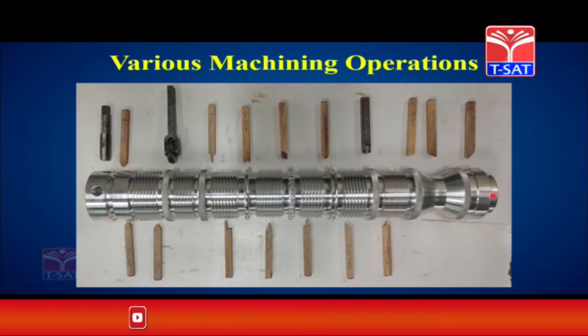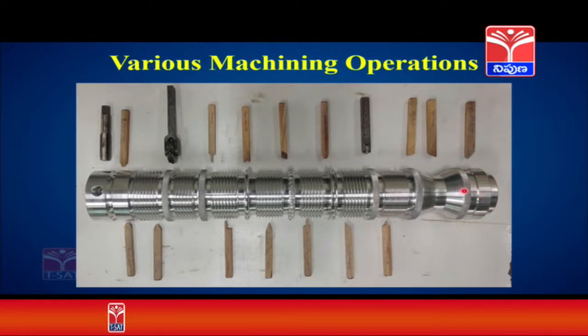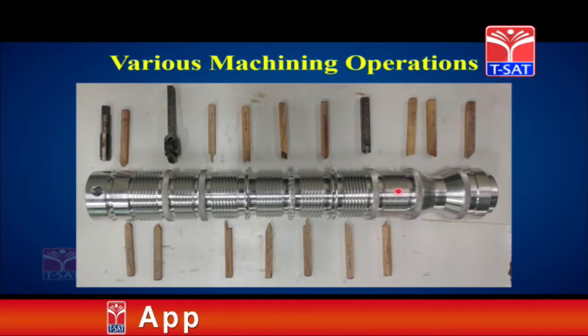Then this one is the step turning. You can see here there is a graduation marking for measuring, and this is straight knurling, a gripping process, and this one is taper turning. Based on the applications we are doing the taper turning operation. Then again this is a straight knurling, and this is the BSP thread, British Standard Pipe, used in chemical industries, aviation industries, almost all shipyards, etc.